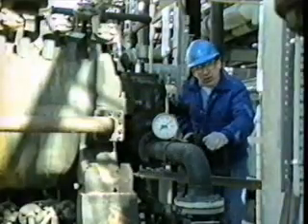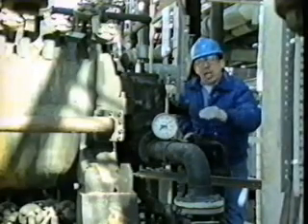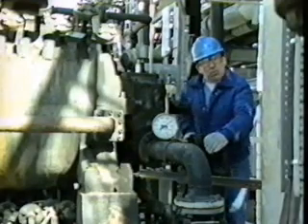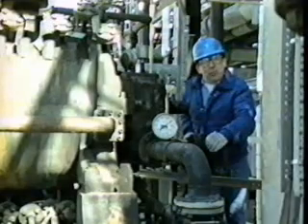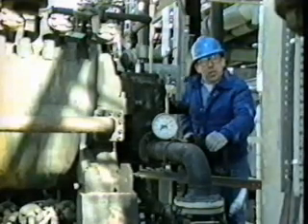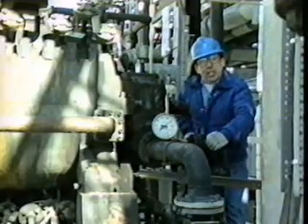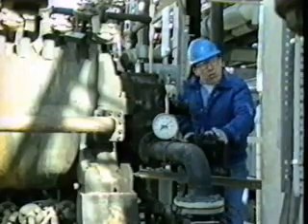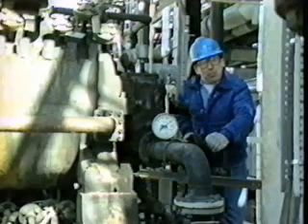A thrust bearing failure can be caused by thrust reversals that occur from the rapid and violent recirculation of the gas. Sometimes these thrust reversals are so violent they can exceed the load capability of the thrust bearing, causing it to fail. This combination of thrust bearing failure and overheating can be catastrophic to the centrifugal compressor. So, some kind of protection must be used to prevent this from happening.